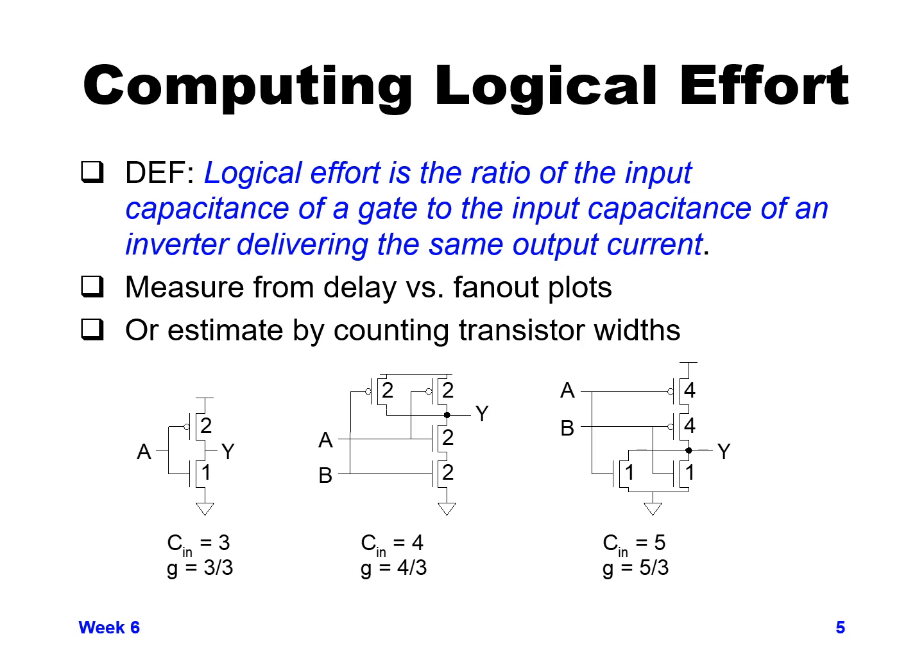So in computing logical effort, first of all we need to know the definition for logical effort. And the definition, logical effort is the ratio of the input capacitance of a given gate for each input to an inverter that would be delivering the same amount of current, so the same equivalent resistance of an inverter. So we need to look at what the input capacitance of the gate is and then divide that by the input capacitance of an inverter delivering the same amount of output current.